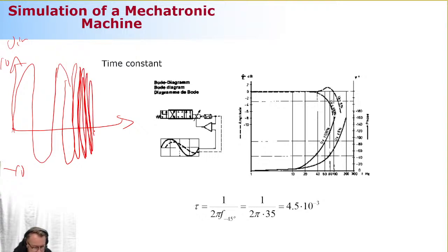Like this. You're able to follow my drawing, which is not the highest possible quality, but you understand what I'm trying to say here. At some point, the signal can do it really, really rapidly. No limitation, but the spool cannot. If the frequency becomes extremely high, at certain points the spool is saying, this is it, I had enough, I'm off the game. When it's off the game, it gets confused because the signal does not correspond to its actual position. And this is where we can see how fast this valve is.